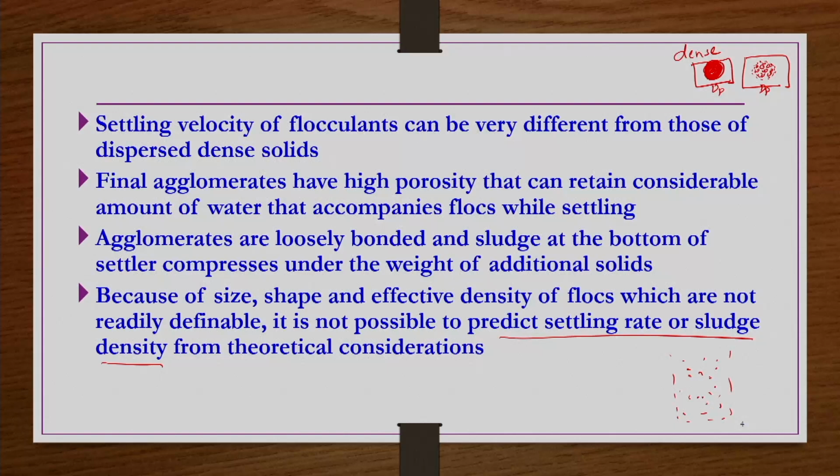So here the effective volume of each particle is different in general. If you do flocculation, agglomeration by adding flocculant, they may form agglomerates like this of different size and different shape, because we are doing it in situ in the process. Their size and shape are different, and their effective volume would also be different because of the nature of how they form by loosely packing these individual particles.